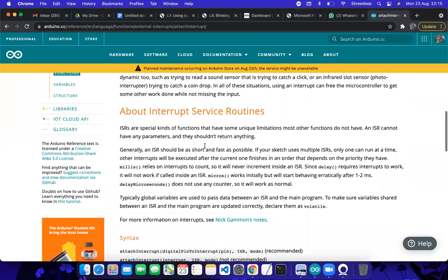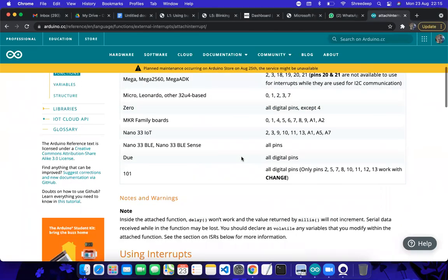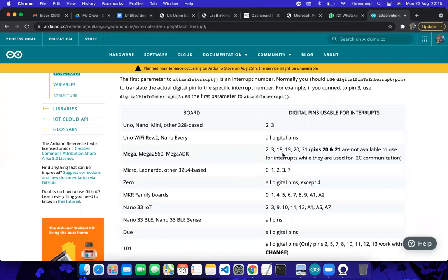See, this is all about the Arduino Uno. But if you use the Arduino Mega, there are a lot of other interrupts. For example, the Arduino Mega has 6 interrupts. So 4 to 6 interrupts are available for the other Arduino boards. For ESP32, all pins are interrupt pins, mostly. Modern day processors like STM32 and PIC, 90% of the pins you can use as the interrupt.